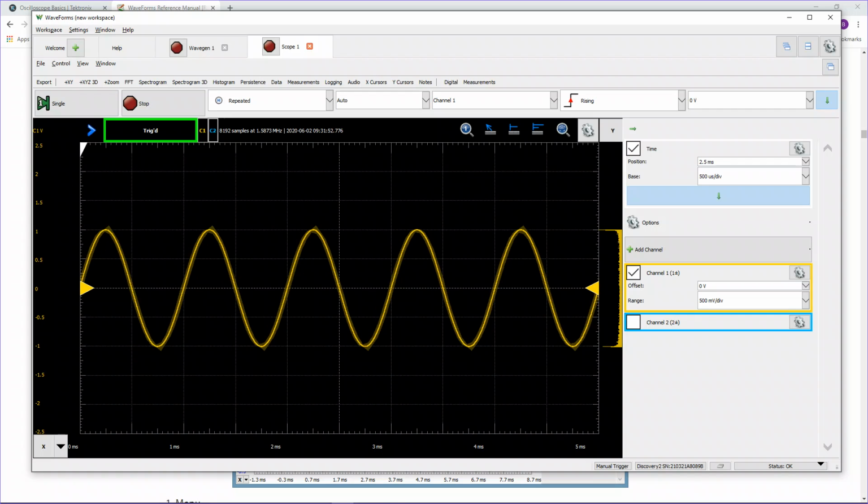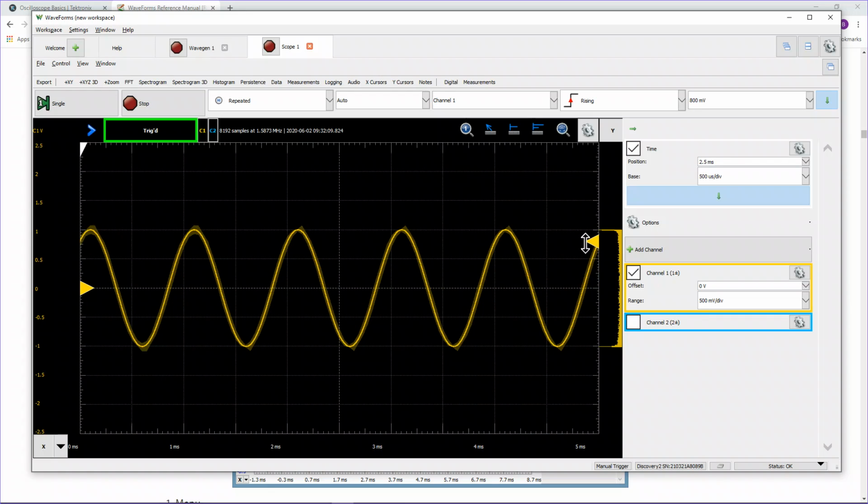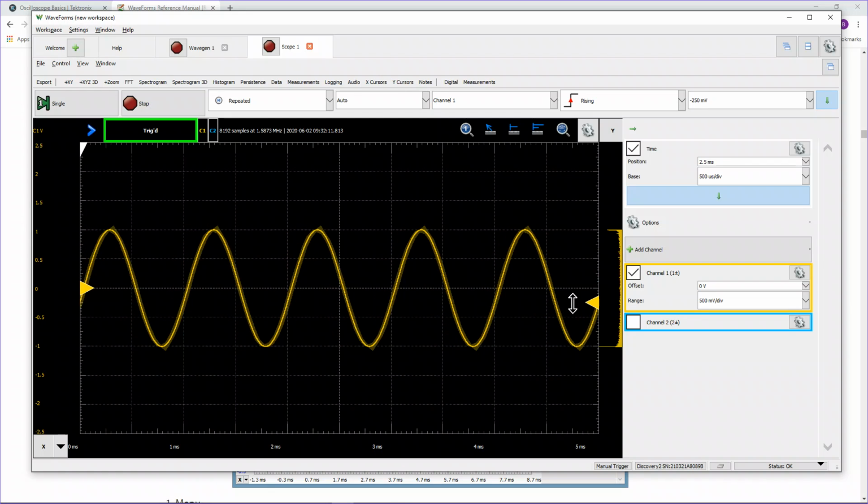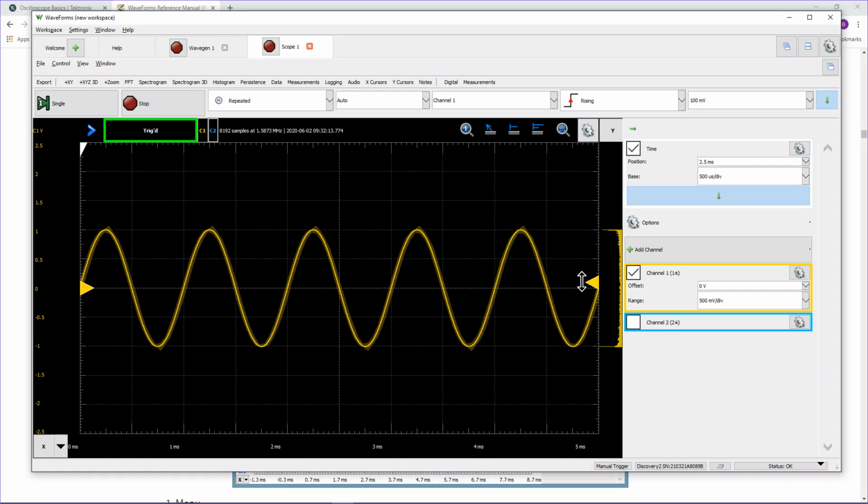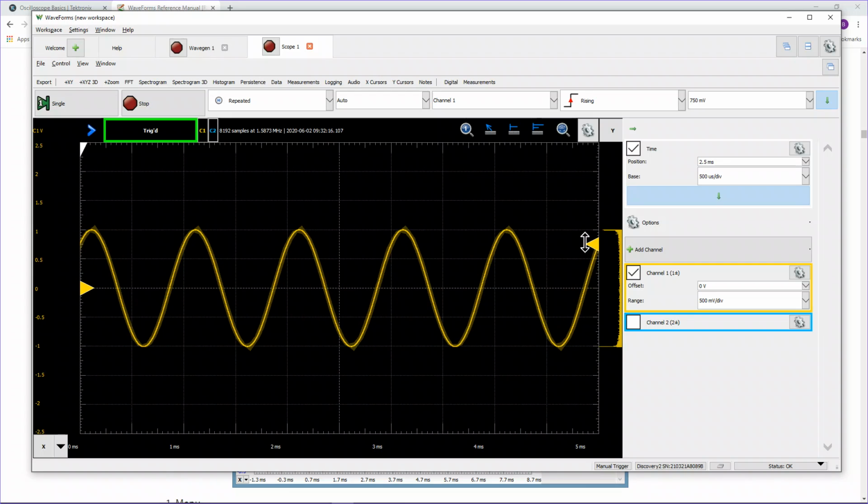So this waveform is repeating over and over again. I moved what they call the trigger point over here to the left side of the screen. And I'm going to play, and that's what this white arrow does. And triggering means, when do I start taking the waveform? Well, this arrow adjusts when I do start taking the waveform, and it's called the trigger point, and this is the voltage level for the trigger point.